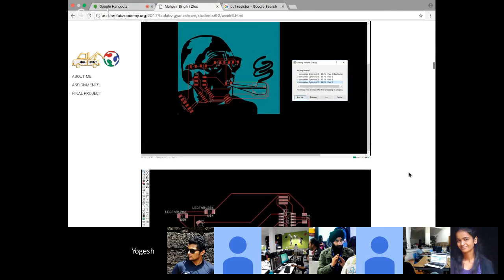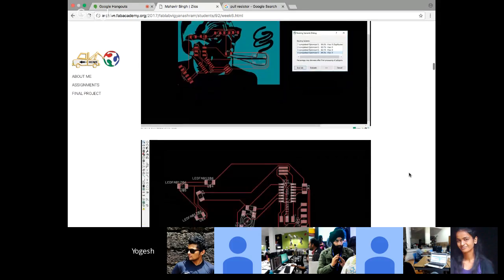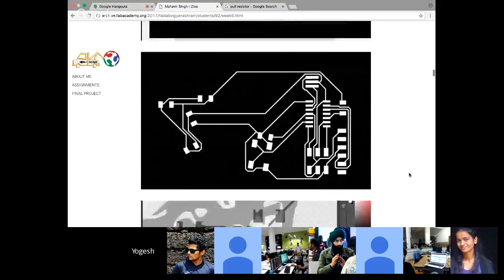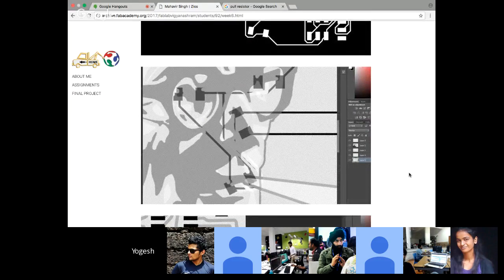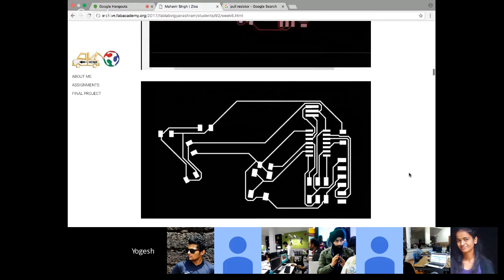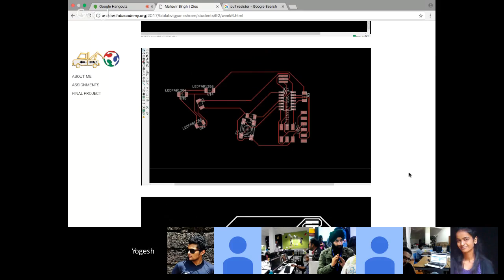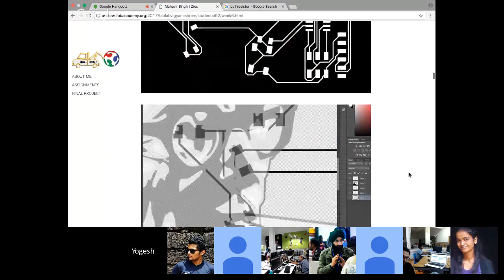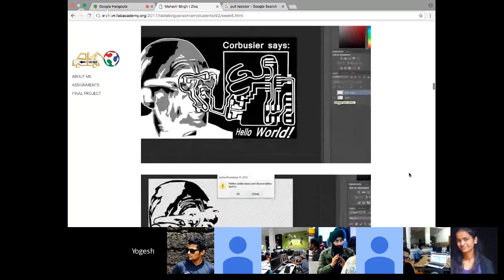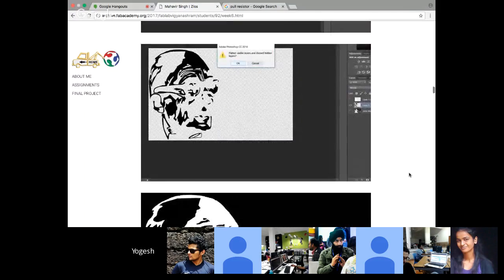Installing the Fab library and then putting in the components, and I did 3 or 4 tries. I imported this as a BMP, switched off a few layers to get this. With this side by side, I try to arrange the components and try to auto route and see if I'm getting something like a 100% solution. So a few alternatives I tried. The first alternative didn't give a 100% solution. The second one didn't. The third solution did give a 100% solution. So I went ahead with that.